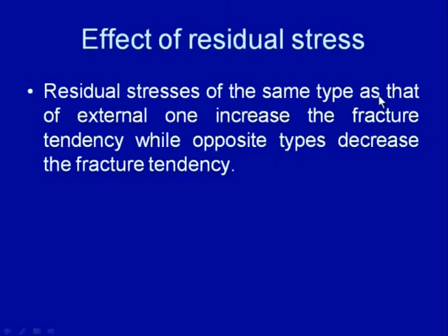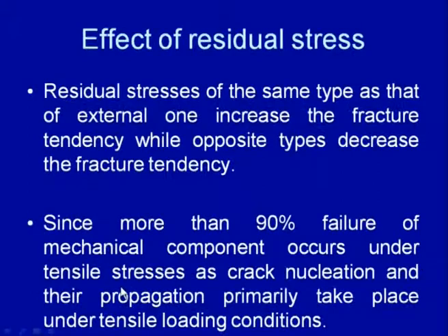Residual stresses of the same type as that of the external one increase the fracture tendency, while the opposite type decreases the fracture tendency. More than 90% of the failures of components occur under tensile stresses, because the tensile stresses promote crack nucleation and propagation tendency, and therefore mostly the failure of the component occurs under tensile load conditions.